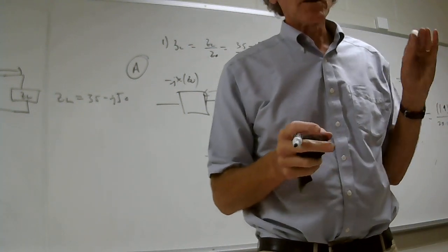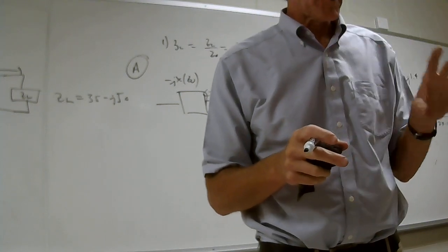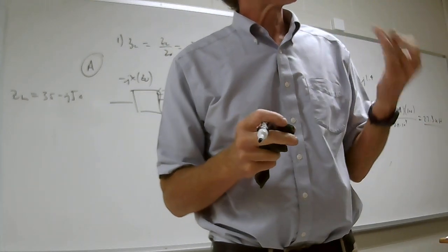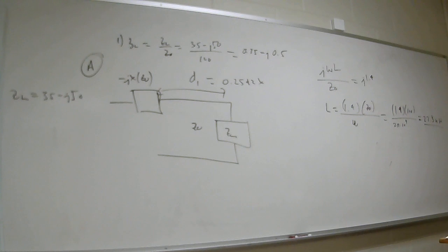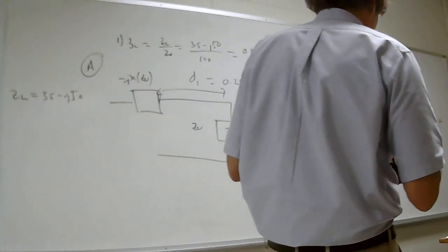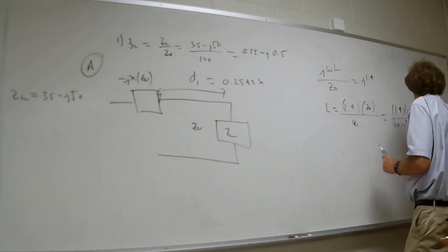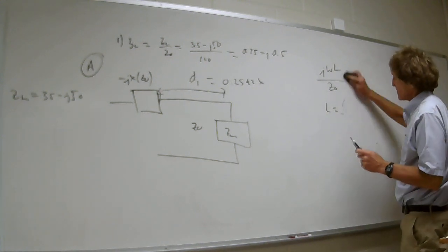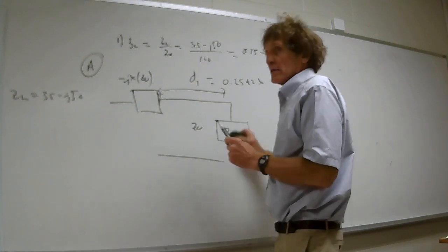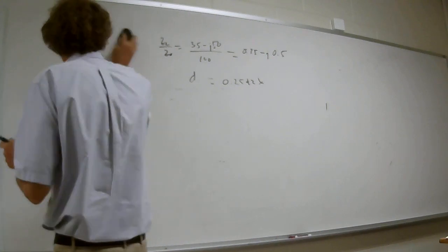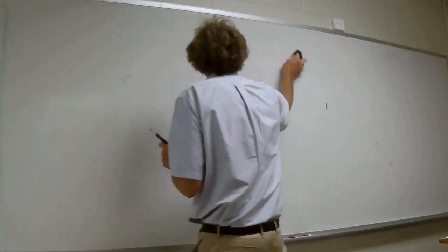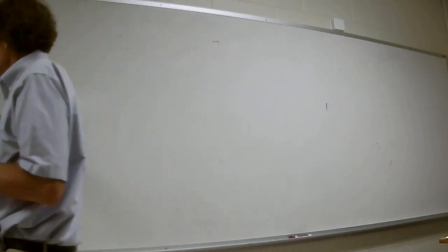You're going to see shortly we can do it with a shunt element or a parallel element too, but we'll be working in the admittance domain. Does this make sense to you, everybody? Impedance matching is used all the time, and it's used everywhere. All the time and everywhere. So next, after that, you got another problem for me, don't you? Surely you do. All right, now I'm going to erase this. Because we're going to get into impedance matching using shunt elements. And that's kind of neat. Parallel. This means shunt is parallel. And we do that in the admittance domain, not the impedance domain. So fun. And Dr. Wintler's book has a lot of examples.